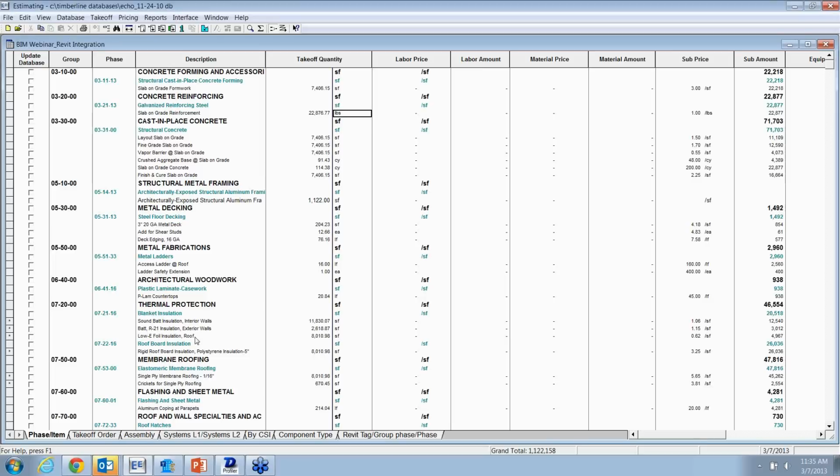We have a feature called WBS codes. Those codes are ways of tagging the building. So it might be building A, B, C. It might be floor 1, 2, 3, or room A, B, and whatever. The concept is that as you're doing your estimate, and I use a drywall wall type as a great example, I have the ability to tag that inside of BIM, and I take it off once, and I can take all that wall type off, and I can get total